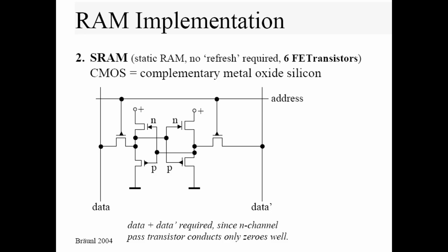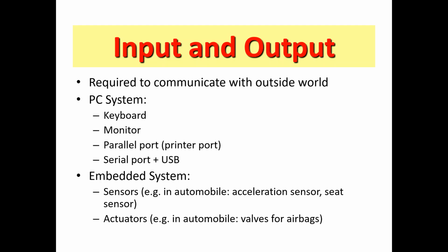As per the applications, 6T SRAM cells are widely used in cache memory in CPUs and GPUs for fast access to frequently used data, embedded systems for storing critical data that needs to be accessed quickly, and mobile devices where low power consumption and high speed are crucial. So this configuration is a fundamental building block in modern digital electronics, providing a balance of speed, stability, and power efficiency.